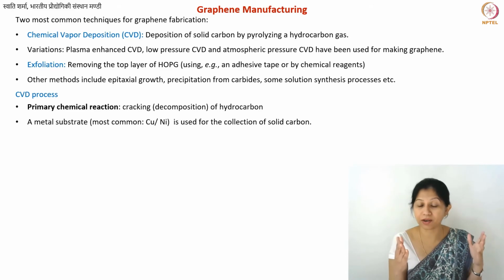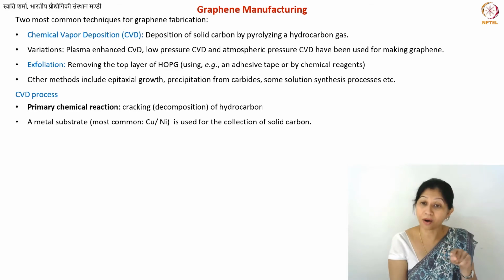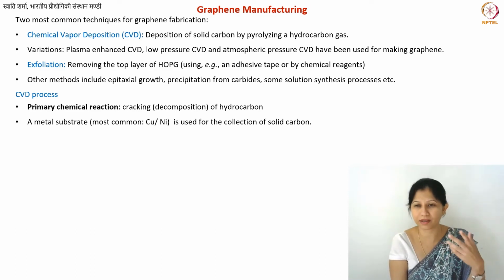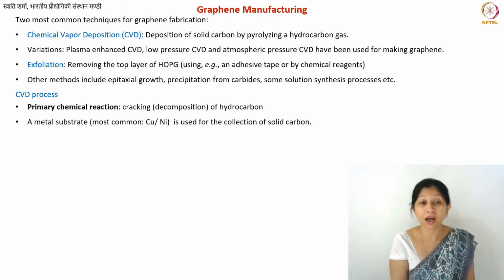This process is very long, and of course it's relatively expensive, so it's only performed for rather high-end applications, for example, some very high-end composite materials, carbon-carbon composites. So in that case, you can perform this. My point here is that you can perform CVD on carbon substrates as well. But in the case of graphene production, in order to obtain only single layers or few layers, and minimizing the number of layers is the goal of graphene CVD, we often use certain metal catalysts, but again, a range of catalysts have been tried out. The most common ones are copper and nickel.